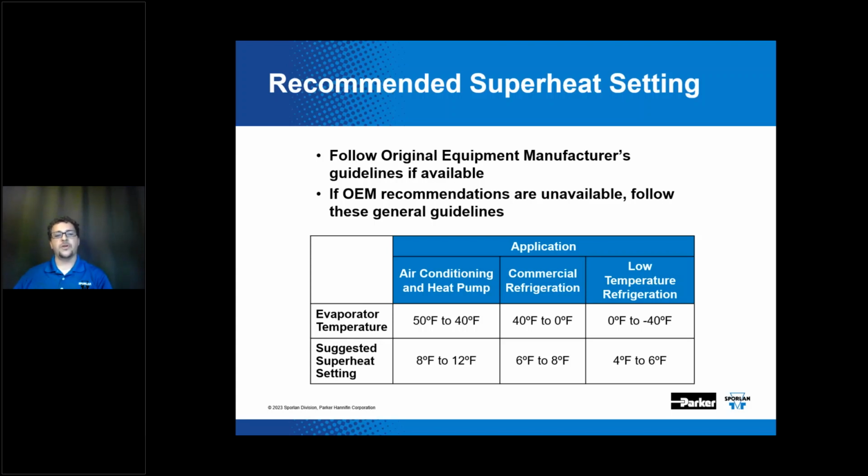In the quick tips books. But regardless, for original equipment manufacturers that have certain guidelines around what superheat they want to see on their particular piece of equipment, it is highly recommended to follow that OEM guideline. But if you do not have guidelines from the OEM, you can refer to our general guidelines here.